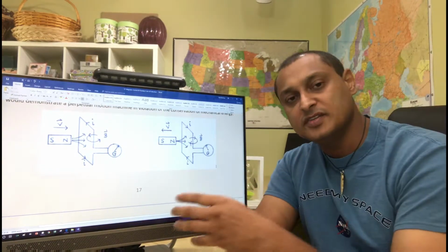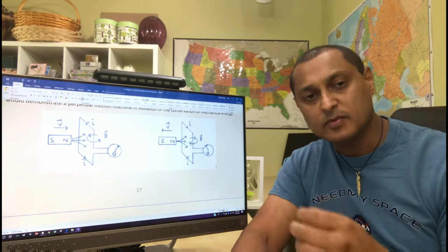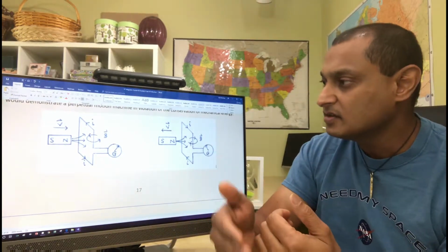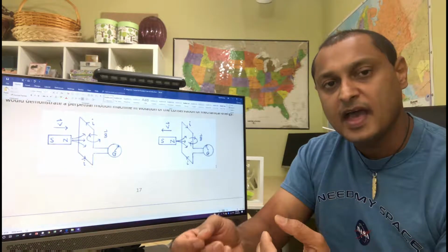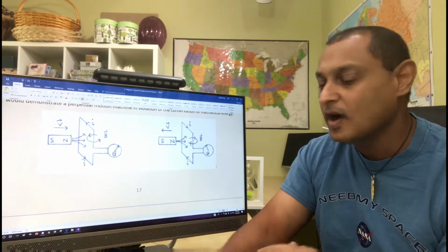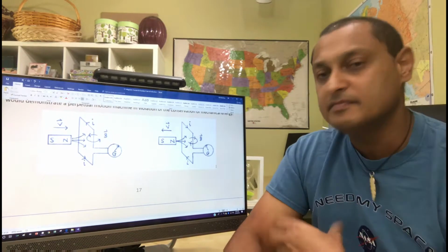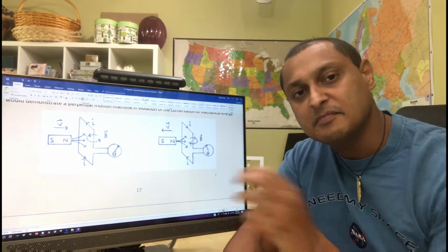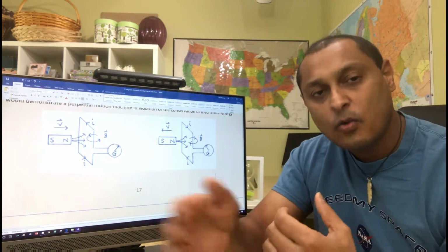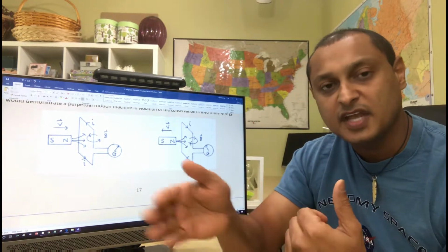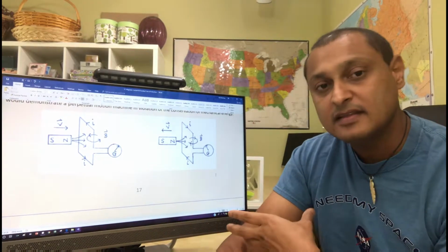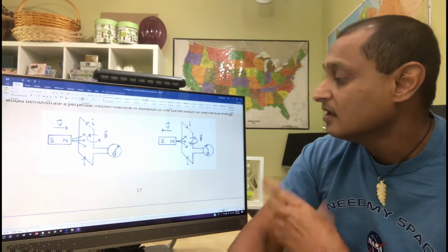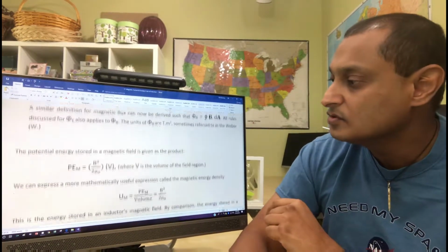As a magnet is plunged into the cross section of the coil and removed, as long as the magnet is moving, the magnetic field in the cross section of the coil is changing, and that induces a current in the wire. So this is Faraday's Law of Magnetic Induction. And such things as the velocity of the magnet moving in and out, that is how quickly the magnetic field is changing in this loop, affects the magnitude of the induced current as well as the cross-sectional area of the coil. That also affects the strength of the induced current.